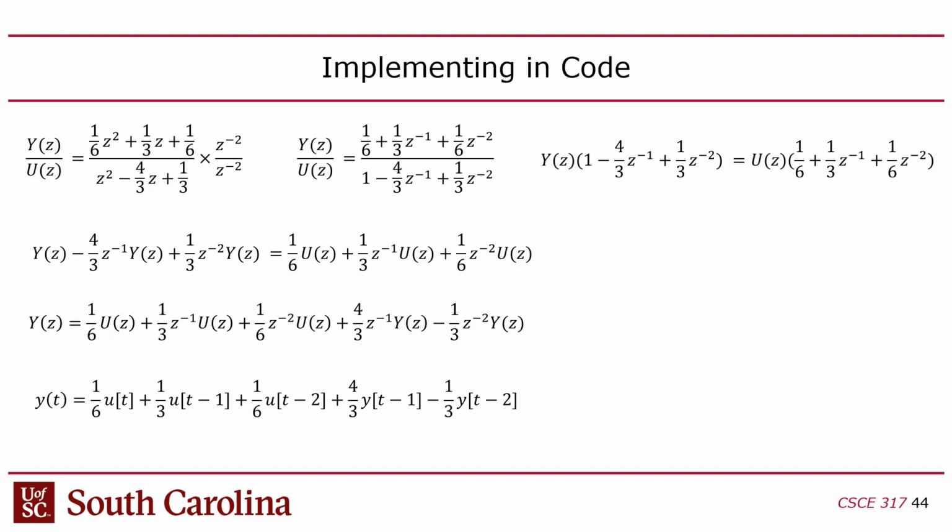The way the math works out is I'm looking at previous outputs, but only up to 2 samples ago, right? Notice that I never have to have that integral that takes me all the way back to time 0. All I have to look at, as long as I have the last output 2 outputs ago, the current input, 1 input ago and 2 inputs ago, I'm golden.